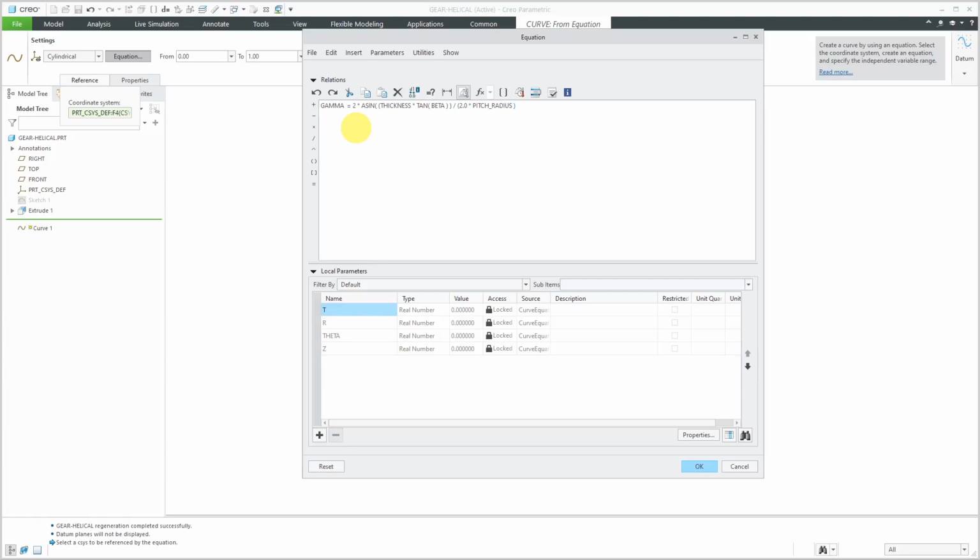And now we're going to calculate our z coordinate. This is going to be equal to thickness times our t, independent variable for the equation, minus 0.5. Let me move my mouse over.